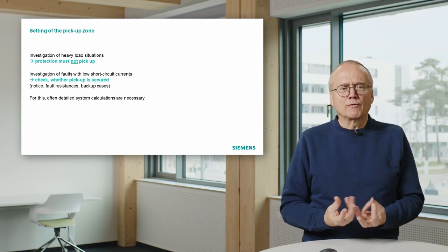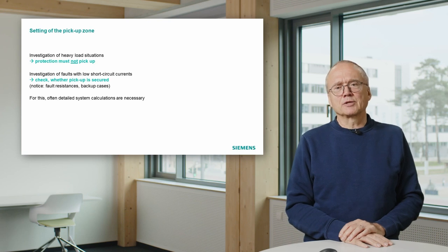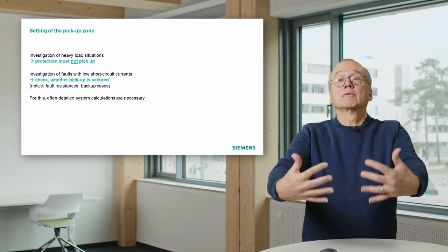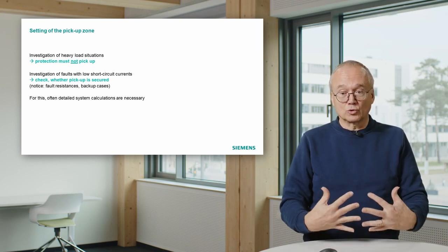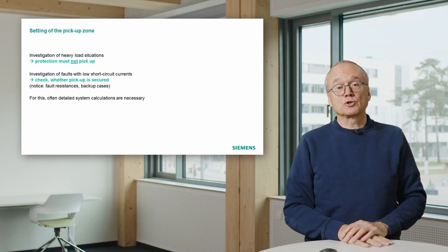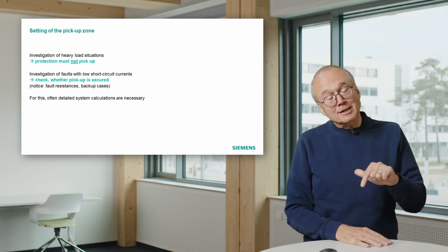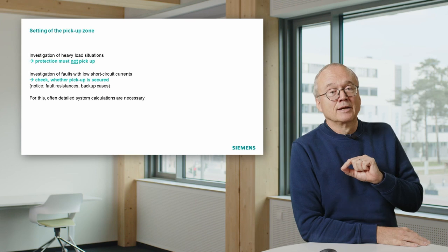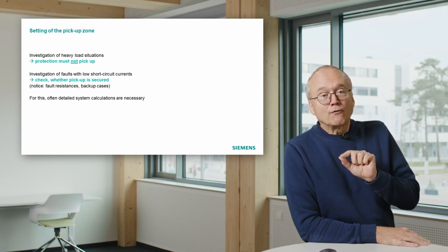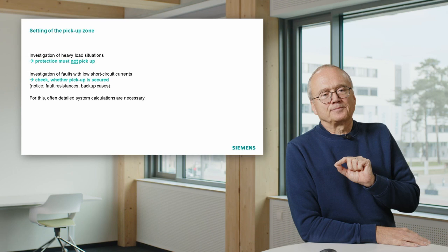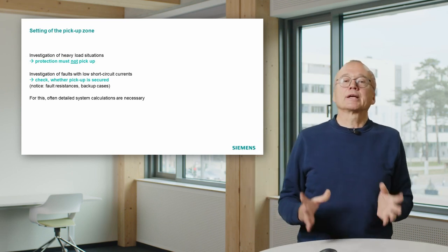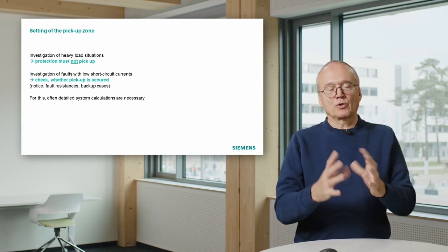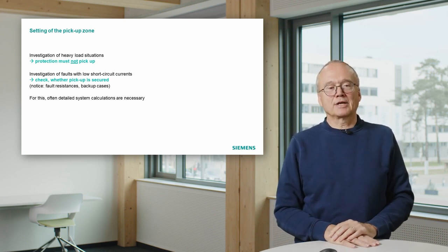You have to find out really all critical situations which may occur, not only today, but also in future, because you want to define the settings now, and they should also be valid in a couple of years. And the other thing you also have to investigate is faults with low short circuit currents. That means you have to take into account fault resistances, and you also have to take into account backup cases. And also there, detailed calculations are necessary.